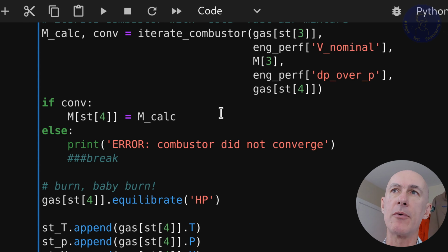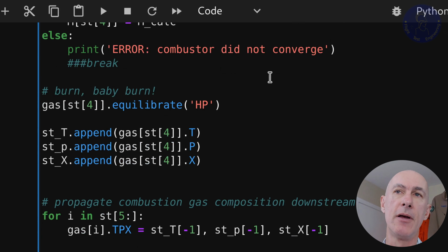And just a quick recap, what do we have so far? We have fuel to air gas mixture at a slower speed with the combustor pressure loss applied. So now we burn it. In Cantera, this is really easy. Just run the equilibrate method at constant enthalpy and pressure. This will take in the mixture we had, and using the reaction mechanism we chose in our n-dodecane YAML file, it's going to run a rather complex solver using the Smith-Missen VCS, or VCS for short, minimization technique.